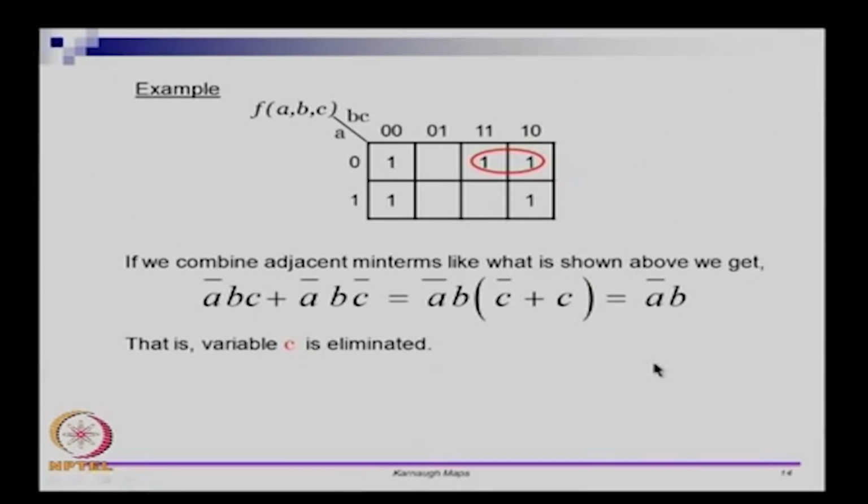So, this brings me to the end of this module. What we saw in this module was we were able to take Boolean expressions and write them in terms of K maps. Even though the K map is in some sense similar to the truth tables being rearranged, it gives you something really powerful: the adjacent rows and adjacent columns, if you combine them, are going to knock out one variable and so on. We will use this fact in a lot more detail in the next module.